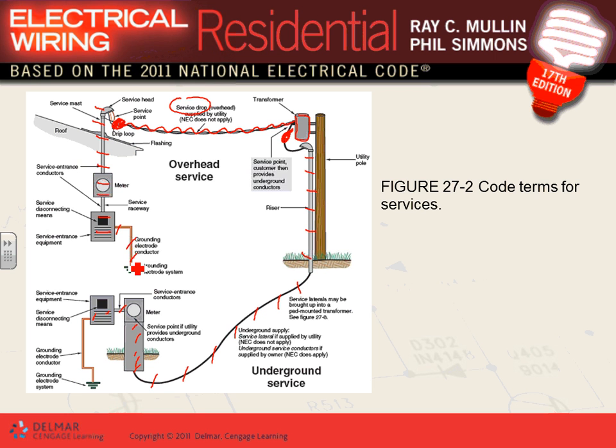I will bring to your attention, guys, the service entrance conductor came through the pipe, into the meter, out of the meter, into the service disconnect, and then we do grounding and bonding. Can you guys see that? What you do here, Matt, is you take your neutral and ground it right at the service. In the US, guys, we run a grounded neutral. So when you bring the neutral from the utility, the first thing the code requires you to do is to ground the neutral.